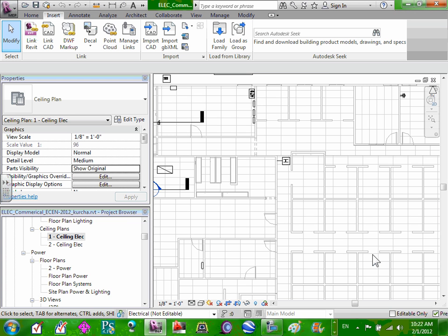If you want to say a few things about egress lights and exit signs, Joe: what we're using right now is bug eyes. Though we have a generator backing up the building, we're not assuming that this generator is an emergency source, meaning we're not required to come up within 10 seconds. So that's why we're backing it up with bug eyes everywhere. Bug eyes are meant to get you out of the building. They have batteries in them that will last 90 minutes.